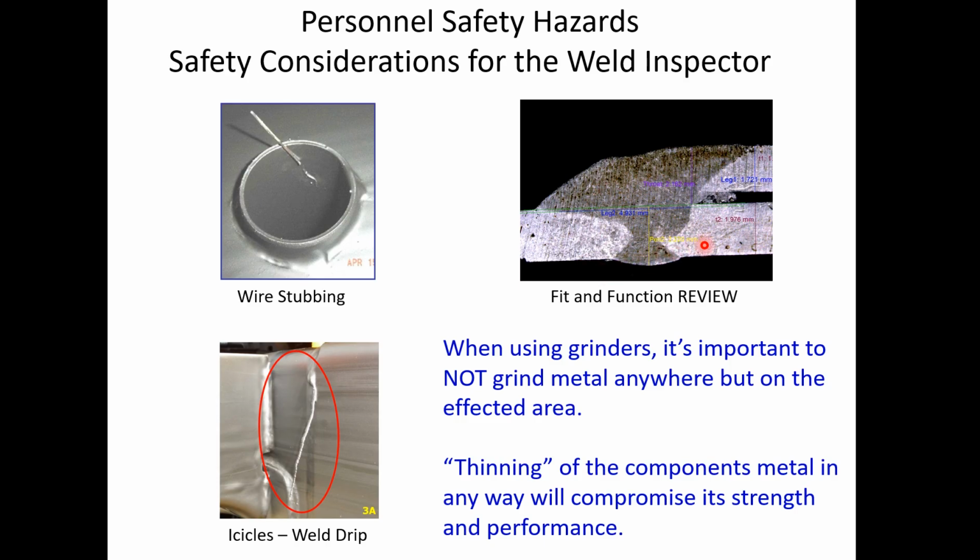Now, normally, these are the types of things that show up on notices later on, right? On station notices that say, there's a problem, we need to look at this. Because they had one go through, but you have to be considerate that there might be a part that has to mate to this part, right? Don't always think, I got a little bit of melt through on the other side and it's okay.